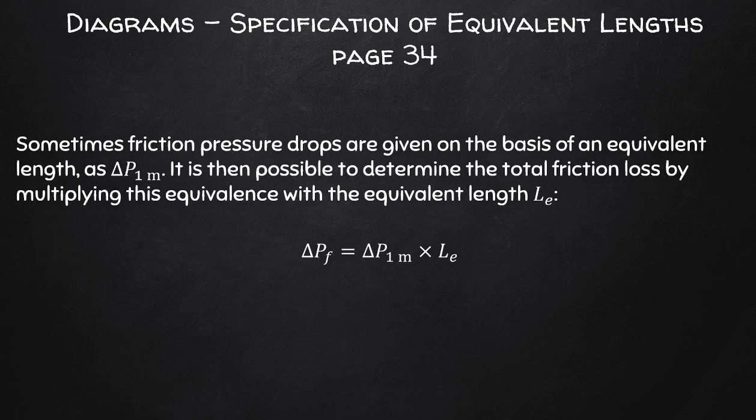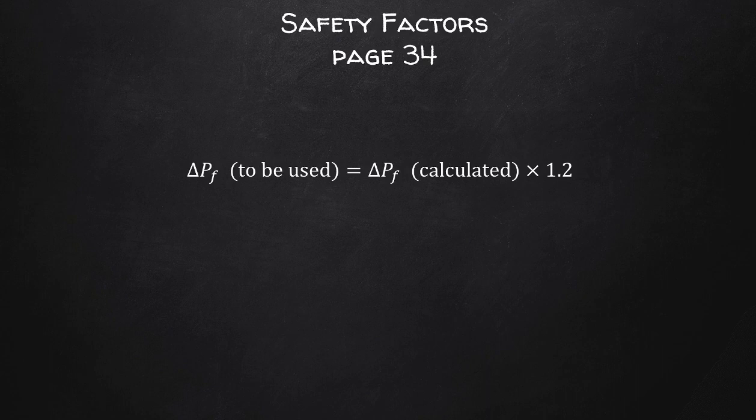Often with older literature, one would come across pressure drops given on a per meter basis of length of pipe. Okay, so it will be per 1 meter length of pipe. The idea here is to then multiply this value by the actual length of pipe that is applicable to your process. We will soon use this as well to complete other piping system design calculations in later chapters. So just remember this definition for now.